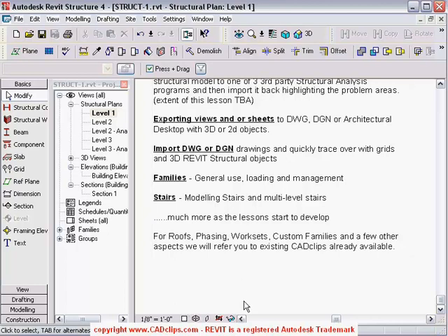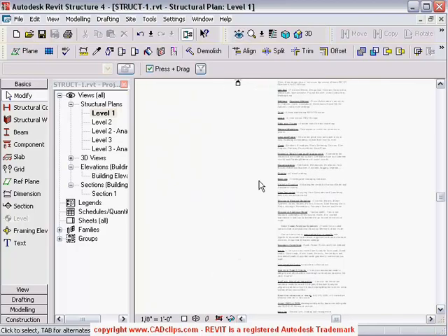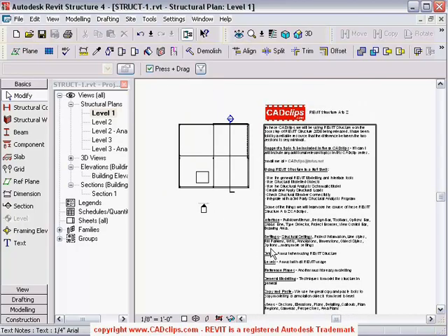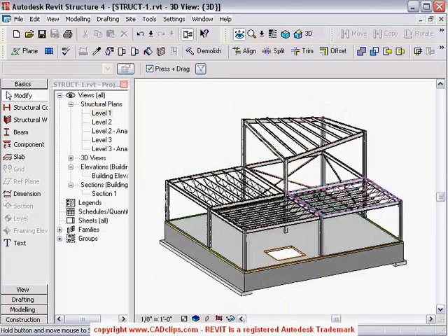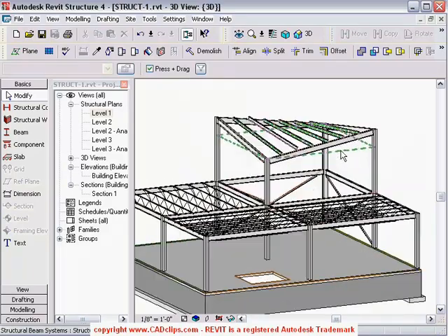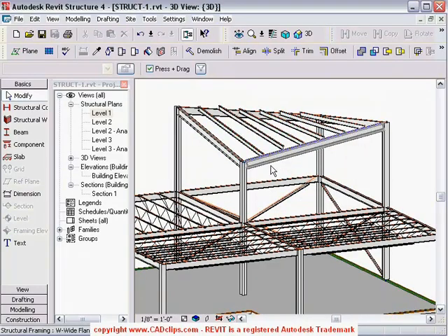So now I've just zoomed in here, and all this is a bunch of text in my Revit model. I'll just have a quick look at my 3D model here, and I've just got a little bit of a teaser here. I'm just demonstrating how you can take a slope beam and tie a beam system, okay, this is a beam system, all these guys, and tie it to this beam, and then if you slope this beam, the whole beam system will then slope with it.